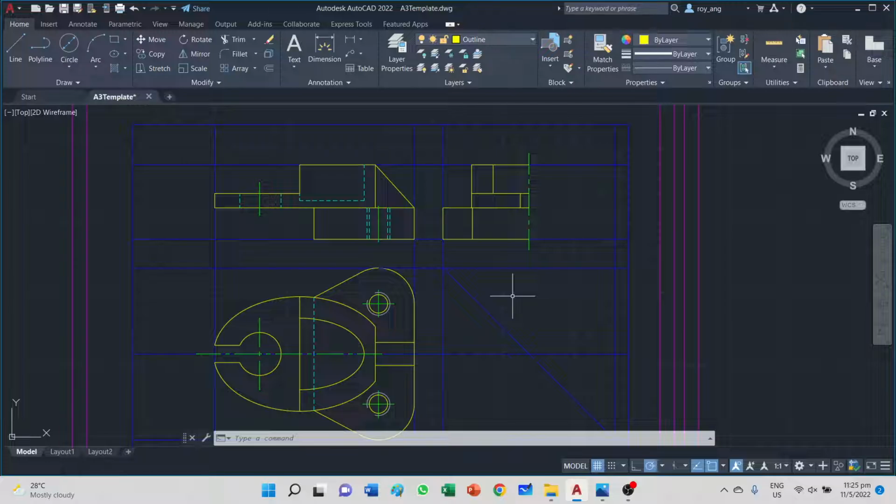And this view is going to be really messy because there are lots of hidden lines. So what we're going to do is we draw the hidden lines, focusing one feature at a time. Okay, so I'll focus on the feature here. Alright, and this is an outline that we see, but this here will be a hidden line.